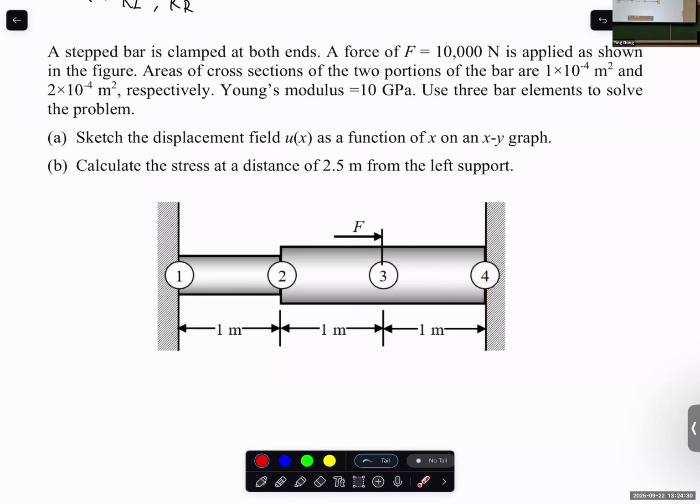But of course, again, based on mechanics of materials, we know that stress can also be calculated from the strain. So what you need to do is, I have the displacement here, and the displacement here equal to 0. I have the original length equal to 1. So the elongation here is a contraction, of course, a negative value. Delta in this section times Young's modulus equals stress. Both of them are correct. So again, this is how to calculate stress and what the 2.5 means. Don't get confused about how to use 2.5 in your equation. You don't really need this 2.5.